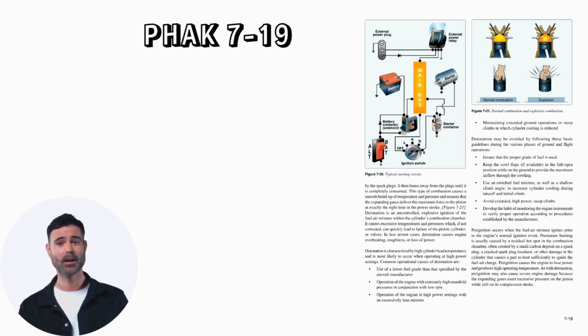Detonation is an uncontrolled, explosive ignition of the fuel-air mixture within the cylinder's combustion chamber. It causes excessive temperatures and pressures which, if not corrected, can quickly lead to failure of the piston, cylinder, or valves. In less severe cases, detonation causes engine overheating, roughness, or loss of power. Detonation is characterized by high cylinder head temperatures and is most likely to occur when operating at high power settings.